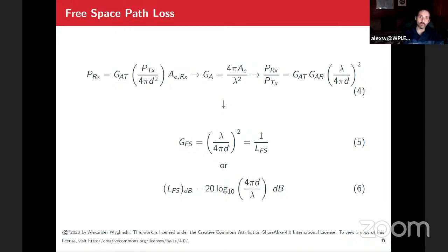And then we use some sort of instrumentation to collect what the receive power is. And we say, are we golden or is something wrong? Theoretically, these equations are pretty good. They capture the physics of the reality around us pretty well. So if something's off, especially if it's like 30 dB off, there's something that requires additional digging around to make sure there's not something quite resonating well.